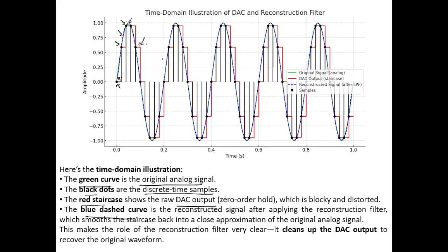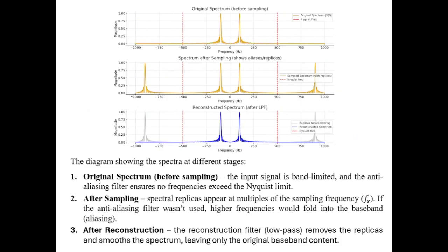So it gives you all this information in this same curve. Okay, so if you look into the spectral component, this is the original spectral component. If you consider this as the Nyquist frequency, you get some positive frequency, and each positive frequency is associated with a negative frequency, so it has come over here. Then when we have sampled the signal, this positive frequency component has got mirrored in the negative one.